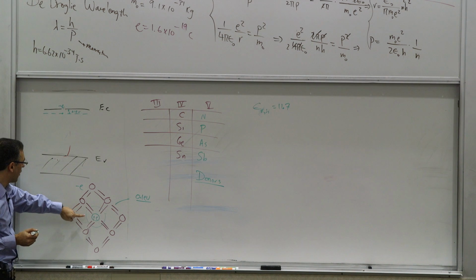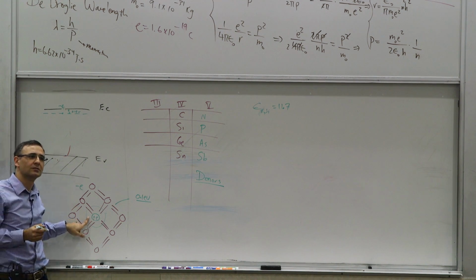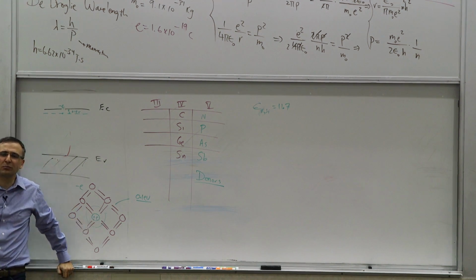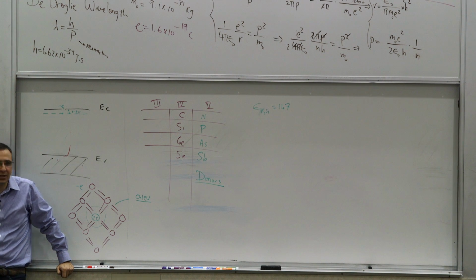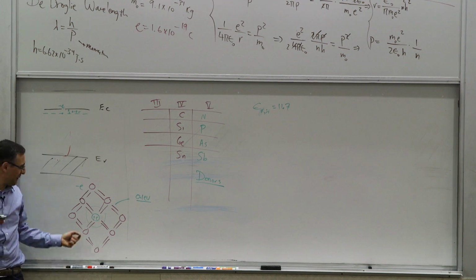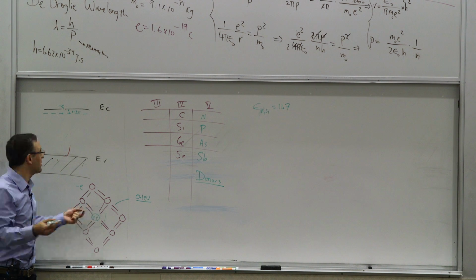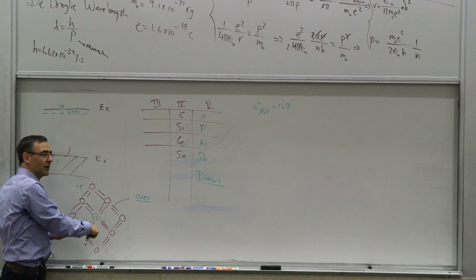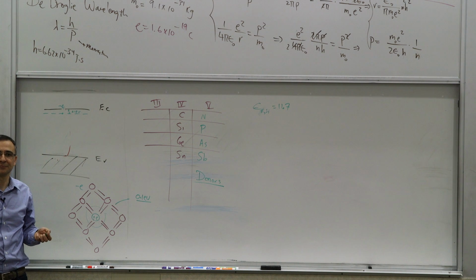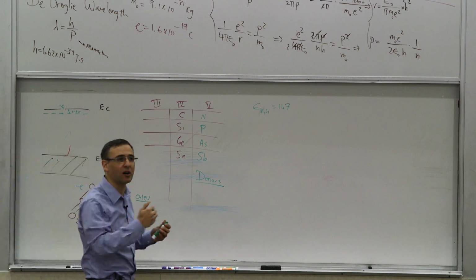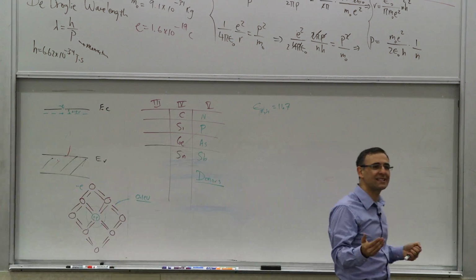But is this also a hole? Why is it not a hole? What is different between this and a hole? Yes, why can't it move? Because this positive charge is contributed because of what? Because of its nucleus, right? So this is fundamentally different, as you pointed out. It can't move. This guy is bound here. So yes, there would be a positively charged area here, but it's not a charge carrier. It cannot carry any charge. All it does, it just sits there.